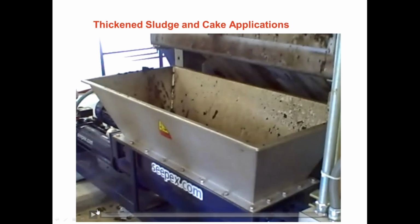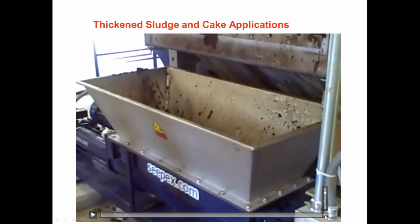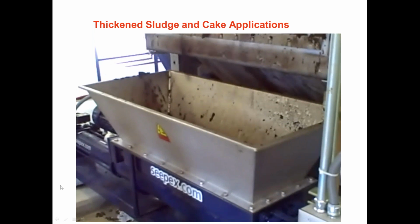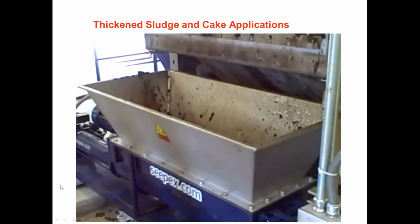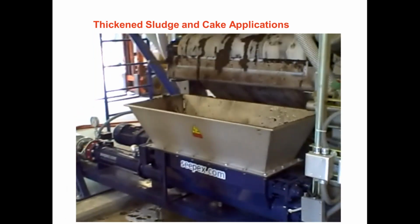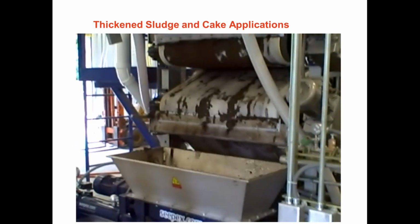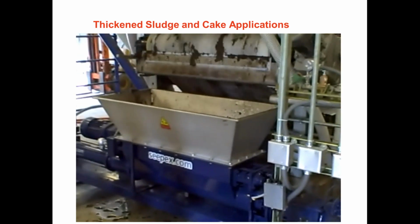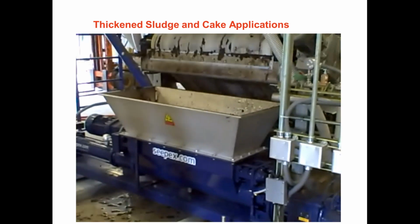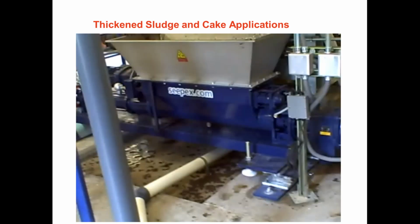Moving on, thickened sludge and cake applications. For moving a product such as thickened sludge or cake, the solids percentage increases drastically, sometimes up to close to 50%. You need a special type of pump to move this type of media. Seepex specializes in this sort of application by installing open hoppers and augers onto our progressive cavity pump in order to take a product this thick and pump it over long distances and sometimes very high pressures.